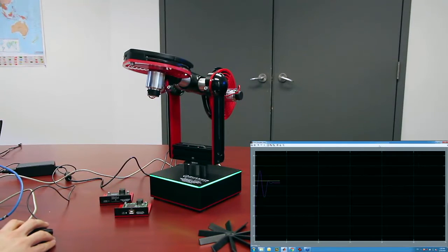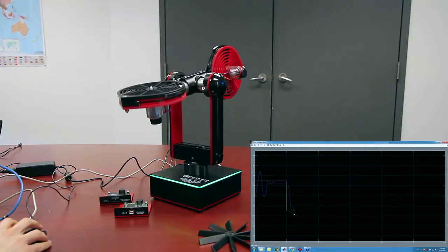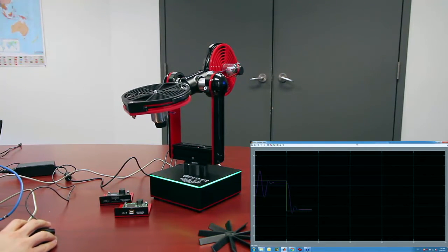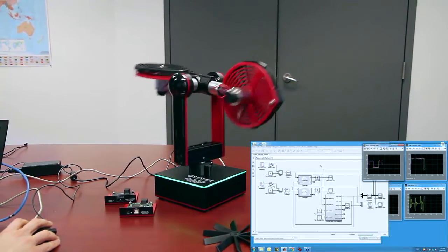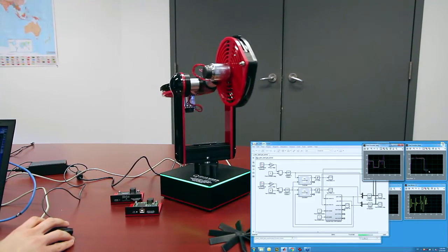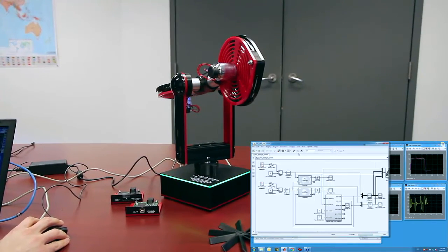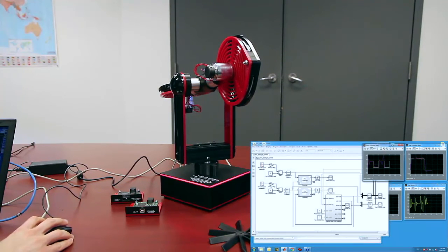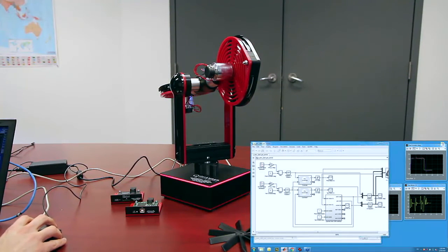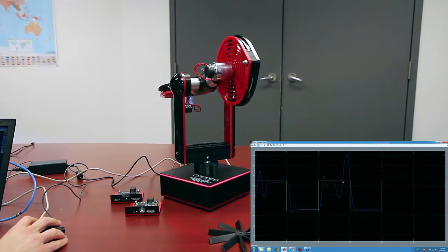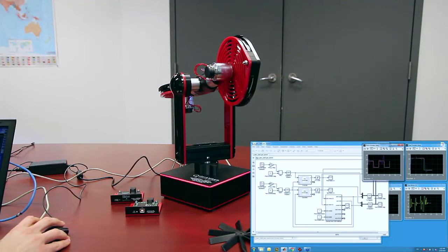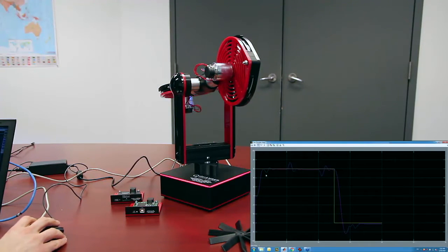Right now, the yellow here represents the set point, and the purple is the pitch measured from the encoder. Note that when it's changing in the yaw, which is a really big movement, I'm just going to stop this for a minute, then you'll see that in the pitch, you get a huge overshoot here, right? This represents the coupling. When the yaw moves, you get this huge motion in the pitch, and you should be able to see it on the screen. So here's the yaw encoder.